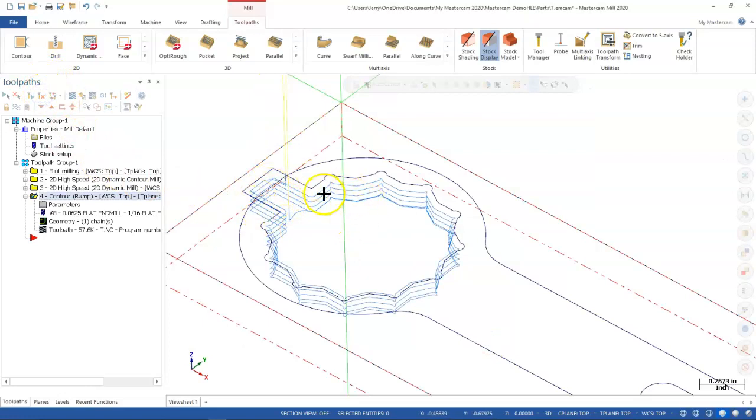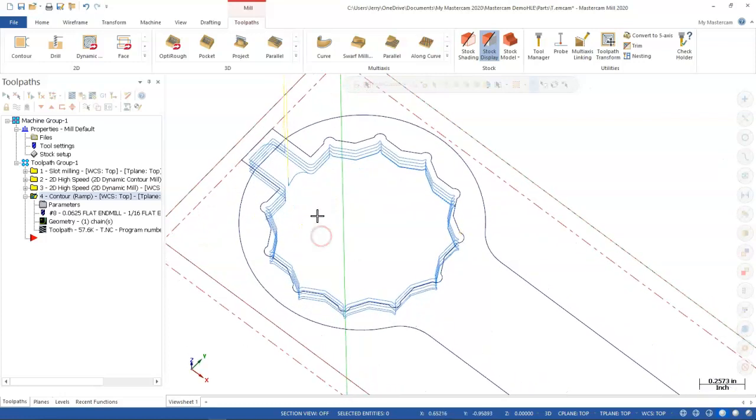All right, so a bunch of little passes, but again, that's having to go into the steel. A 4 flute, even coated 16th end mill is going to struggle a little bit. It's a couple of thousandths difference in the radius, so it's not having to come to a sharp, but it's still plunging in, coming out, removing that material on the outside. I don't know that I want that to be my complete finish. So that gets us a solution, but it probably needs to be refined.